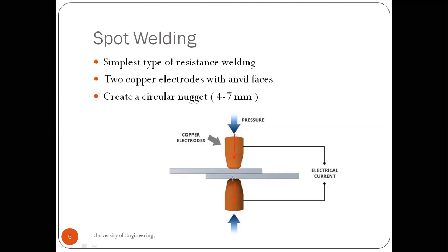and the amount of pressure or amount of time we hold these two electrodes together, the amount of heat generated will be much more. Okay, and we will have a certain amount of melting which will be taking place here, and it will form in the form of a nugget, right? So this will be in the form of a nugget here, right? And these two metals will get welded with each other. All right, so I believe this is clear.